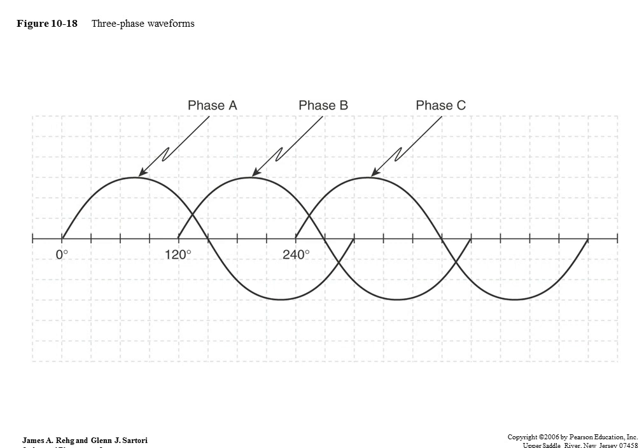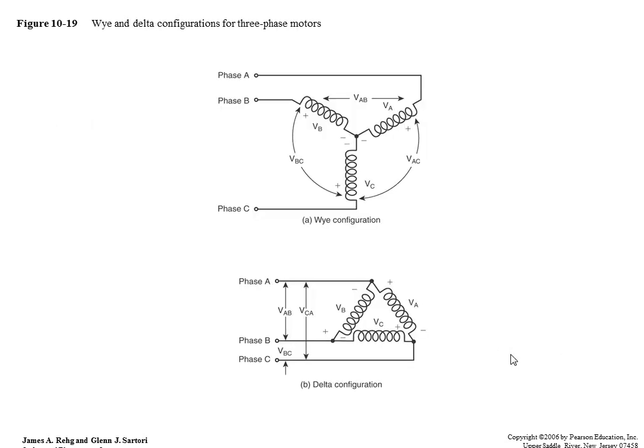I hooked up an oscilloscope and I looked at it. The two that were 120 out of phase, they're the right two. And the next one, if he's 180 out of phase with that one, 120 out of phase with him, then that would be the C guy. If he's the same, he's wrong. If he's the A guy, he's wrong because he'd only be 120 out. So that's what I did. It was trial and error, and that's why they're plugged in where they're plugged in. Want to hose somebody over someday? Plug them into a different plug.